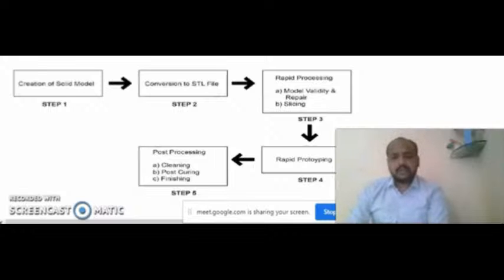See, nowadays 3D printers are used for generating the prototype because complicated shaped parts are very critical to manufacture. These are very critical to generate their dies required for casting. So therefore 3D printing technology is implemented to generate the patterns which are required in the casting procedure. So rapid prototyping plays a very important role to manufacture structures having critical shape.